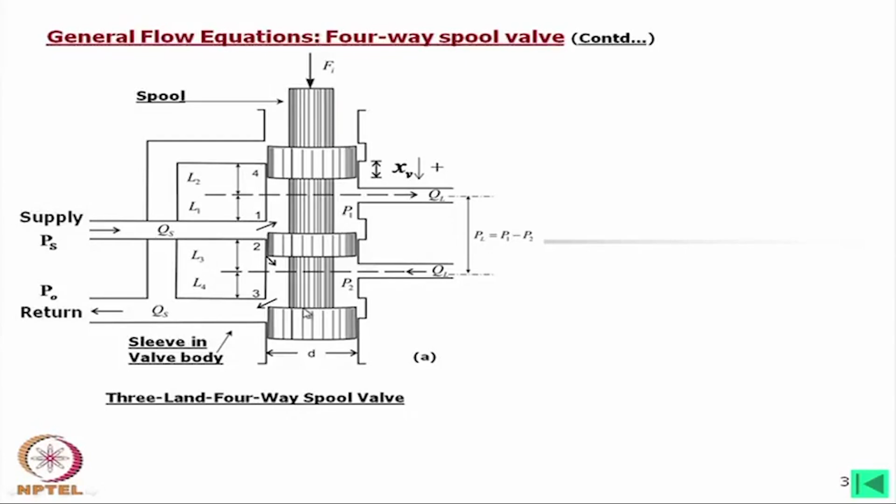One of that is that machining may be difficult, as well this sleeve will wear out with the use of this valve, and if we use a separate sleeve, then we can replace that, whereas if we put this spool inside the valve body, we cannot replace it. So, due to various reasons, we use the sleeve, which also can be accurately machined rather than if we machine the valve body for the bore.